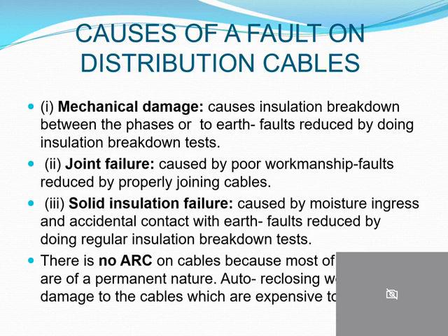Whereas in underground cables, we say there is very little chance of you having a transient fault. The faults that you get in underground cables mean that there is an actual fault, and it could be either from mechanical damage or from your joints, or because of water ingress. Therefore, you should not have an auto reclosing scenario in there, as you will damage the cable further.